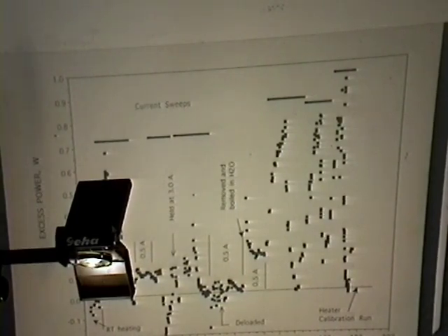The assertion was that when the current was being applied, an AC voltage and current was being introduced on the leads, and my data acquisition was missing the spikes that were being generated. And therefore, since I was missing input power but measuring output power, it would look like excess energy was being produced. Now, there were a number of ways to get at that, and I chose to use the following.